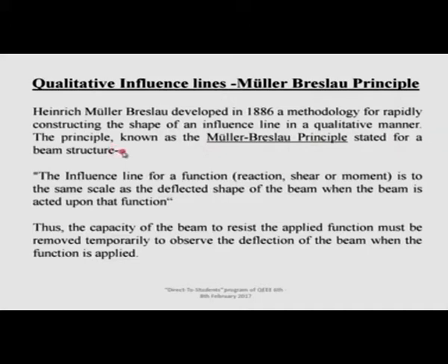Let us have the statement first, then we will discuss what it means, and whether from our perception we can feel it. We need to feel the structures, otherwise it will be difficult in future. The influence line for a function, reaction, shear or moment is to the same scale as the deflected shape of the beam when the beam is acted upon by that function.